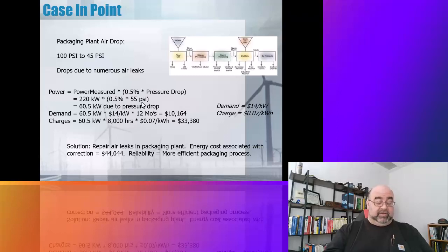Smoke sticks, candles, foam, manometers, and stethoscopes are also possible. Really, what's the point? What does an ultrasound meter cost these days? Even if I'm looking at a 15K meter, you're talking about $15,000. You're going to pay for that probably on your first compressed air audit. Just like what we found with the ESA systems, we went in and took our measurements, and it was like, okay, that pays for this in no time at all.